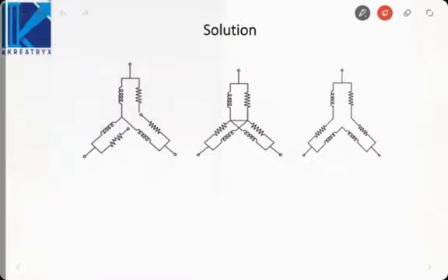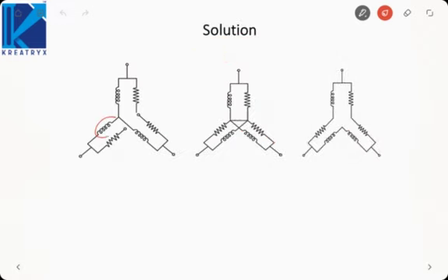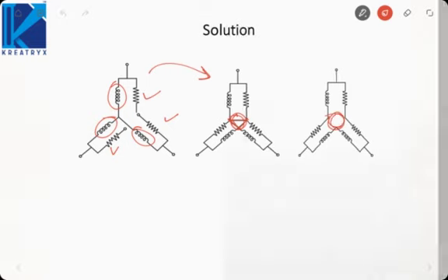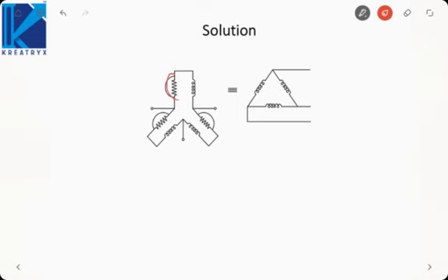How to do that? Like this, the windings are in star initially. Here there are 3 resistances which are disconnected right now. So what I will do is I will connect them. Okay, I am moving from star to delta. First I will connect these resistances. Then I will remove this short circuiting here. This has been removed here. Now what to do is, now short circuit these resistances. Now if you see, this connection is actually delta connection.